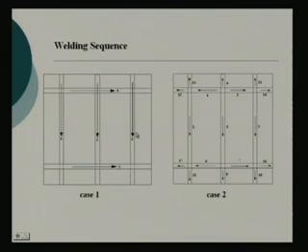So that way the 3 stiffeners are welded, then bring the transverse members, put them in place, and again from one end you start, you weld, cross over the longitudinal, again you weld and finish, right. So from the practical point of view, it is easy to implement. You start the welding and progress till the end.